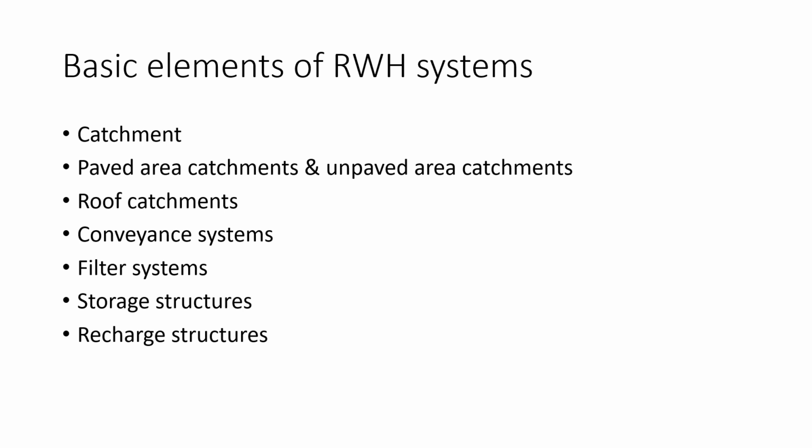Whatever strategy for rainwater harvesting is adopted, first of all, we have to see the characteristics of the rooftop when we talk of these roof catchments. Now, when we talk of GI roofs, if the rain is acidic, metal roofs used in industrial areas will leach metal into the water.